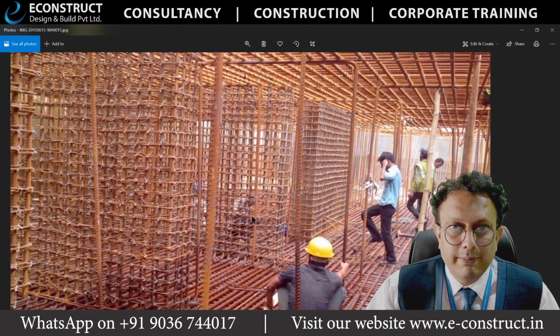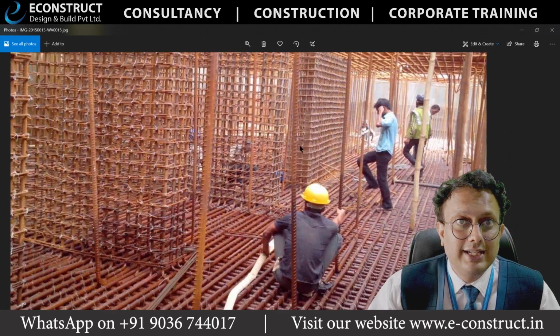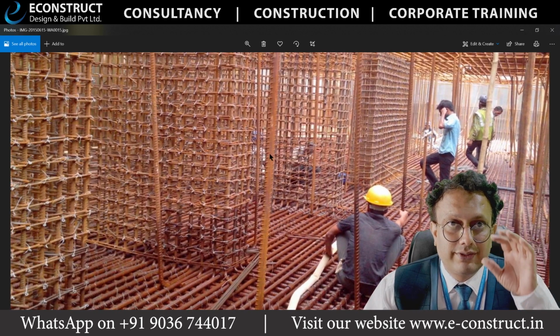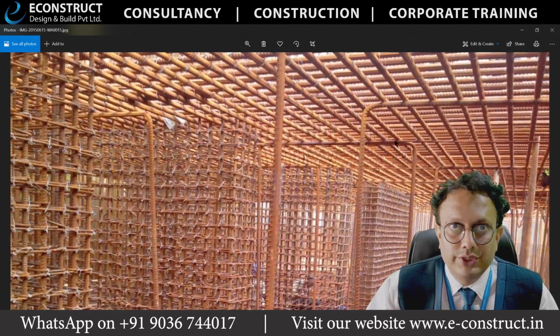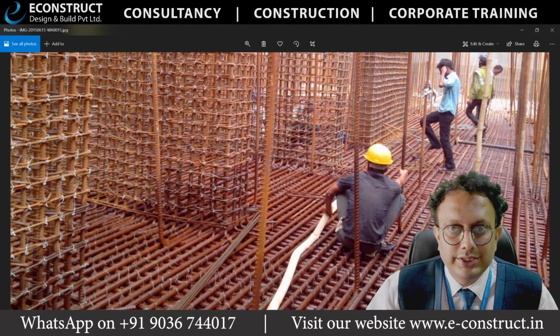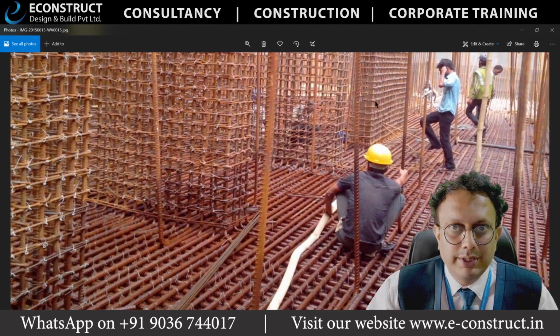Some of you might be surprised, oh my god, this is a raft. Yes, these guys you are seeing are working inside the raft. The raft thickness is in the range of 3 meters. Got it? This is the top rebar which you are seeing here, and this is the bottom rebar which you are seeing here. Bottom rebar is more than the top rebar. Obviously, why? Because of such big shear walls and columns.